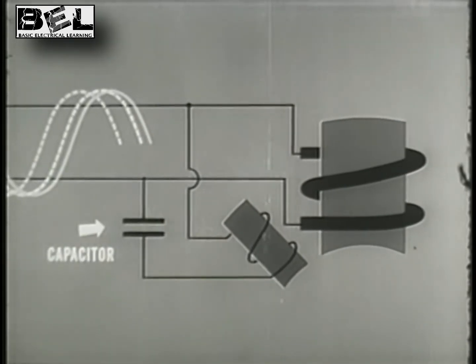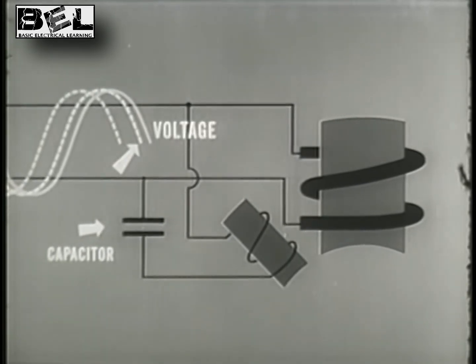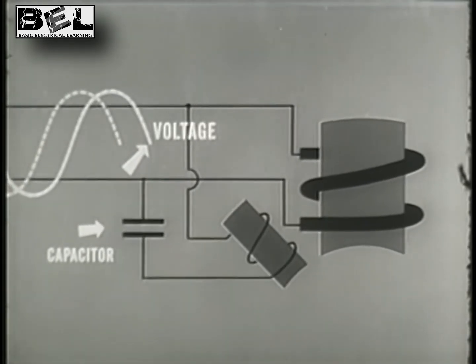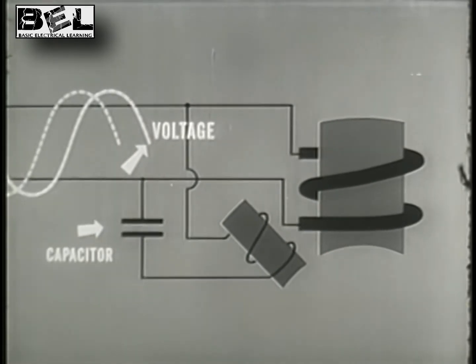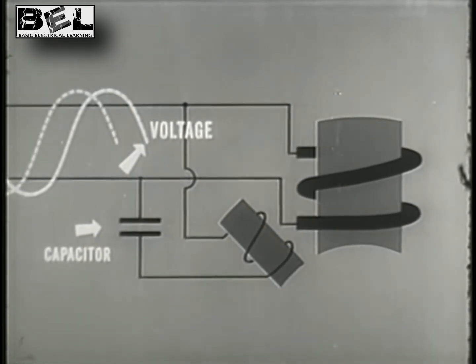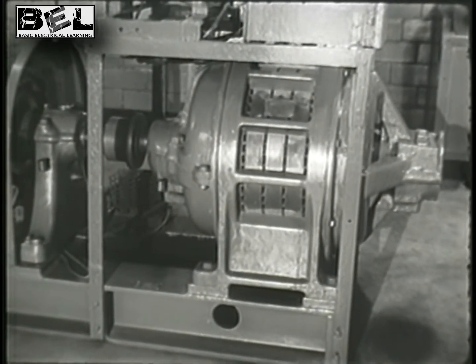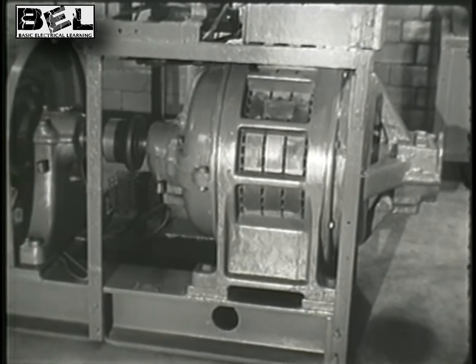In the third method, a capacitor is placed in series with a starter winding. This causes a greater phase shift between the two windings. We now have two-phase operation on single-phase voltage. In synchronous motors, there is no need for relative motion.